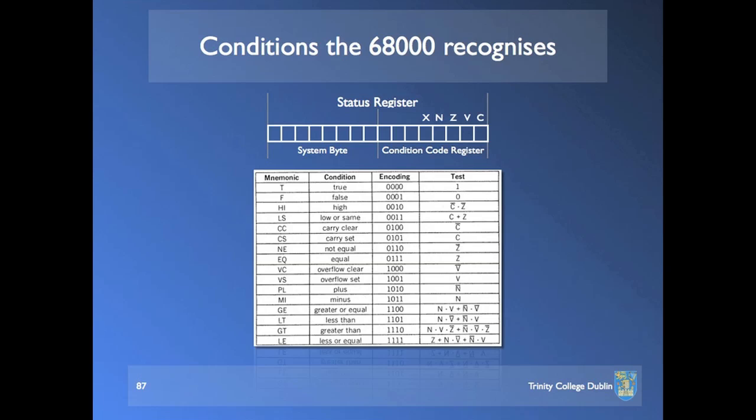We're only going to be using the word part, but there's no cost difference in the 68000. Move long and move word between registers take the same amount of time. So we'll multiply unsigned D0 into D3. So we've got UL times VL now in D3.